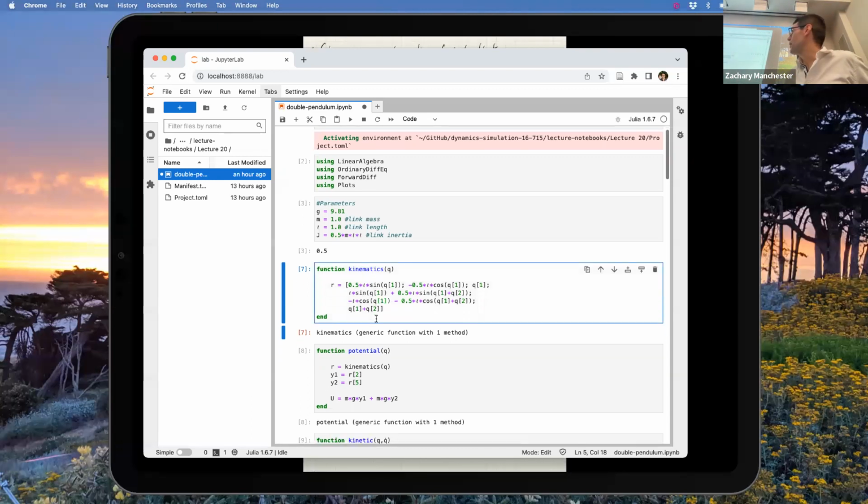Here's the forward kinematics function. I wrote this down by hand. This is the X component. I think I should have drawn the diagram. This is the standard way we write this down, where it's hanging down, and that's 0, 0. The first angle is defined relative to hanging down, so it's different from the picture I drew, where I did it relative to sideways, but hopefully that's not too terrible. So X component, Y component, and then theta of the first joint.